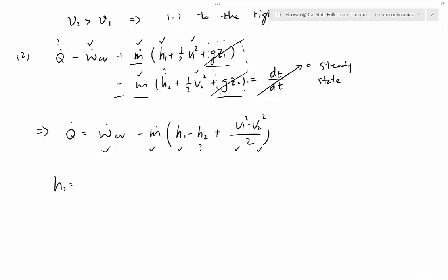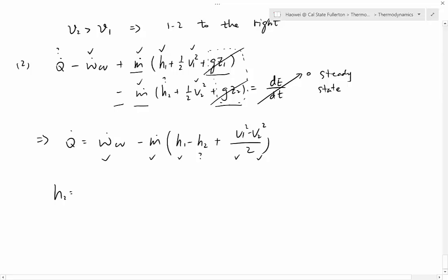What is the phase of number 2? We said before, number 2 is a mixture. How do you look for specific enthalpy H for a mixture? We derived the equation earlier. Just like specific volume, you have two components, point F and point G. So you have two components, H2F and H2G, one for saturated liquid, one for saturated vapor, plus, and then how much vapor do you have? That's the definition of quality, x2. And then how much liquid do you have? That's the rest, 1 minus x2.